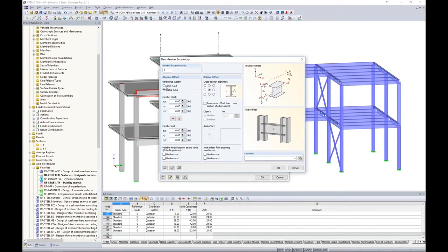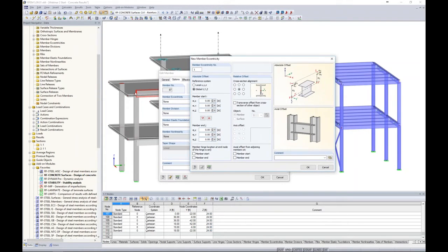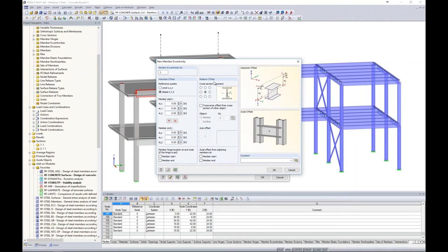And you'll see here that we have not only the local axis system X, Y, and Z for a member, we can also set it according to the global X, Y, and Z. The local might come in handy because if we are modeling a member at an angle, then obviously we want to apply the eccentricity according to the local axes rather than the global. Now we also can apply this movement of the beam in the X, Y, and Z, so not necessarily just vertical eccentricities, but left and right too. So typically with this situation, I would need to understand, well, what's half the depth of my slab, what's half the depth of my beam, add those together, and I can manually apply my eccentricity. But we have automatic features in the program that can do all of that for us.